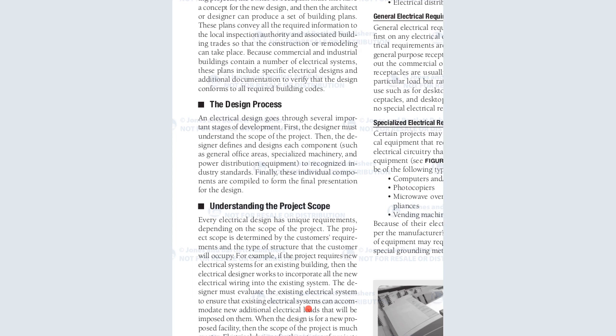What if the building is a new building? Then you're the person who will calculate the loads. You calculate the maximum loads that such a building can carry. If it is a storied building, you have to supply it with three-phase because there can be additional loads with time. It doesn't mean that if the building is starting with a few loads, it will not add.